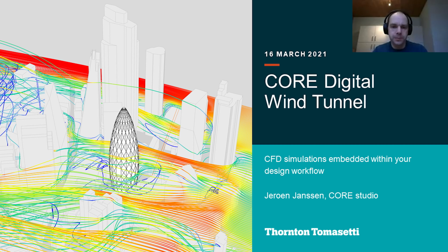That's my opinion. Because it's quite obvious for buildings, let's say, taller than 200, 300 meters, they will have to be tested in the wind tunnel, just because the code requires it, right? The Eurocode, for instance, only covers buildings up to 200 meters. Above that, you need to have wind tunnel testing done. But there's a whole range of buildings between, let's say, 100 meters and 200 meters tall that might benefit from wind tunnel testing. But at the moment, it's not being done, mainly because of the cost of wind tunnel testing at the beginning.